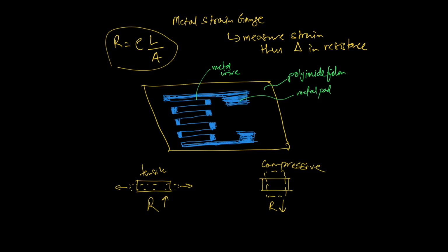So really, you're using resistance as a way of measuring something else. So you use resistance to measure how much light is incident on a surface. You use resistance to measure what temperature there is in the system. And again, you've now used resistance to measure how much strain has been applied or stress has been applied to an object.